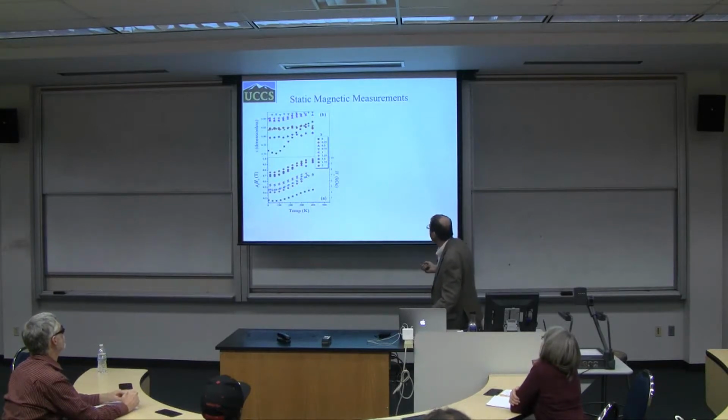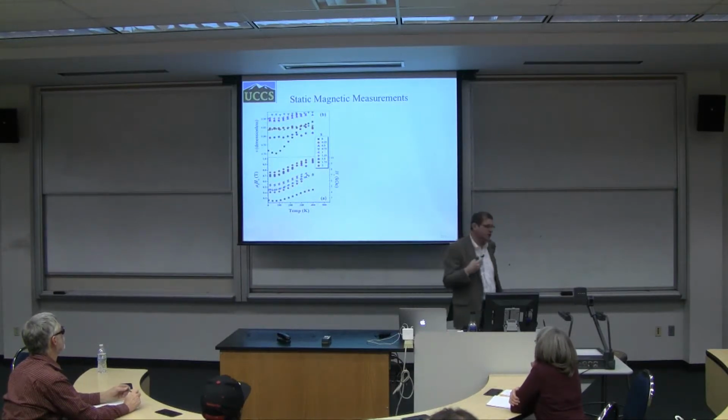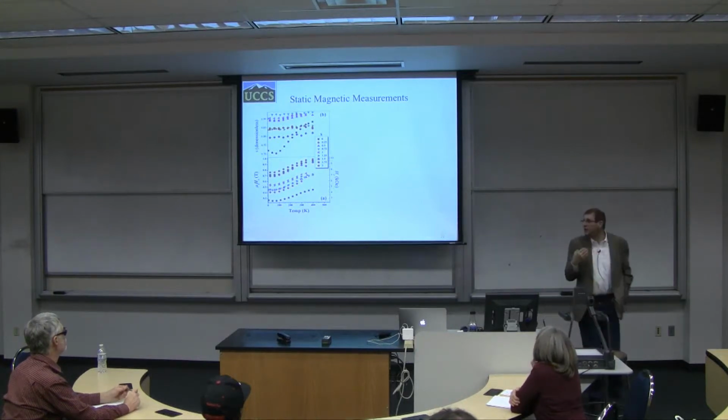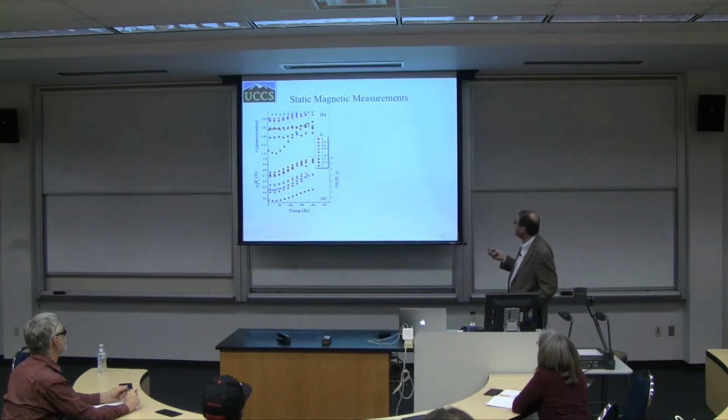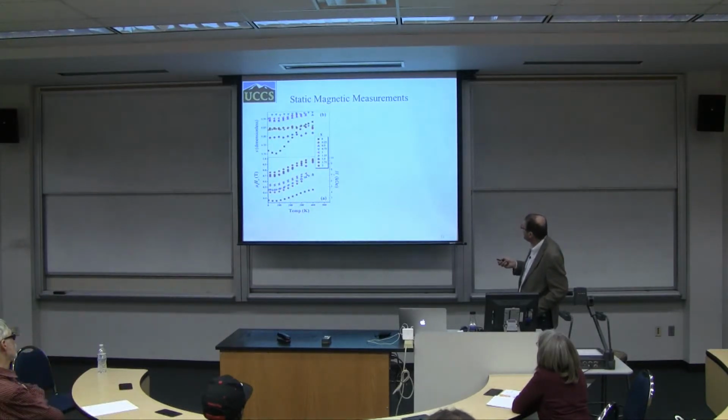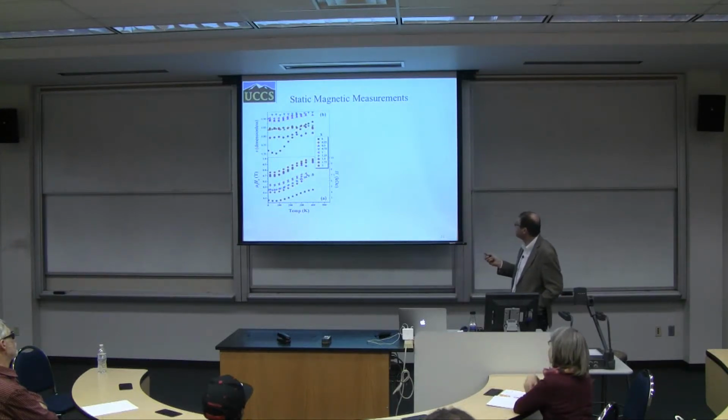What is shown on this graph, so far I was only showing you individual examples, but here we have combined changes in a very systematic fashion, from material with no aluminum whatsoever to a high content of aluminum, when aluminum content was 2. You can see how this thing is changing. Basically what I'm plotting here is the coercive field as a function of temperature, and what is measured here is the squareness. This S is the ratio of MR to MS as a function of temperature.